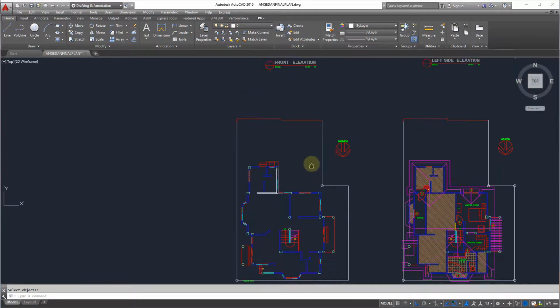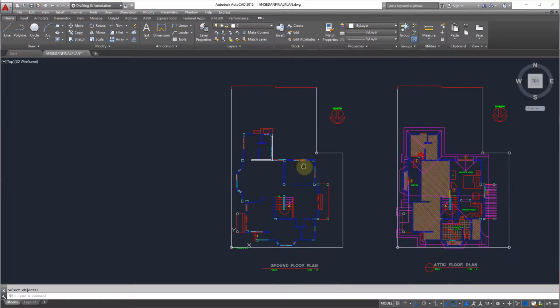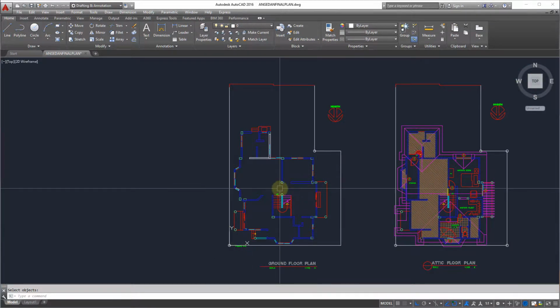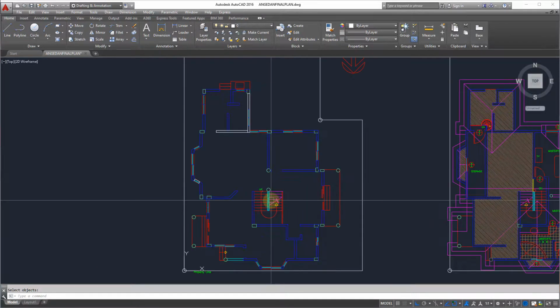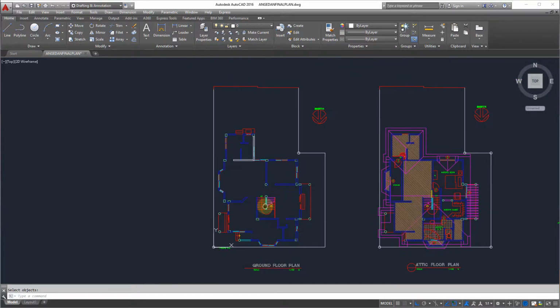Now once you've set your UCS and your unit, that will be the incoming unit to your 3ds Max, the millimeter. So you can block this file. Since we're going to import the floor plan from AutoCAD first, we're going to block this one.